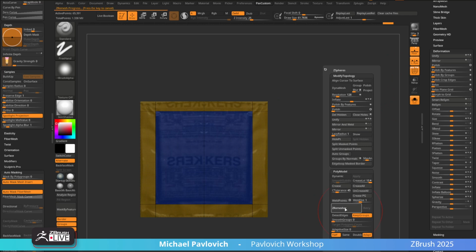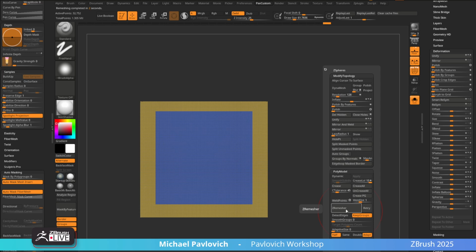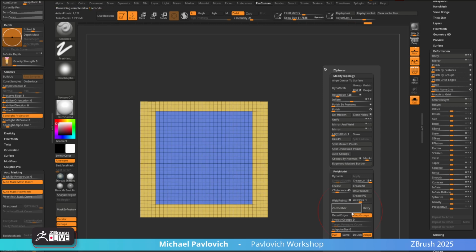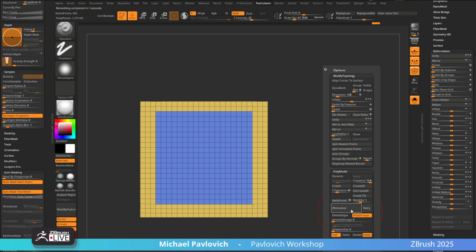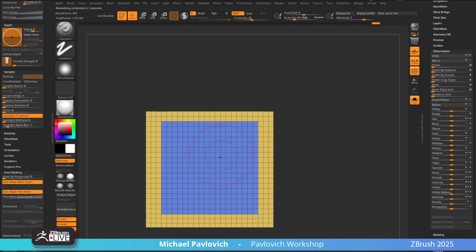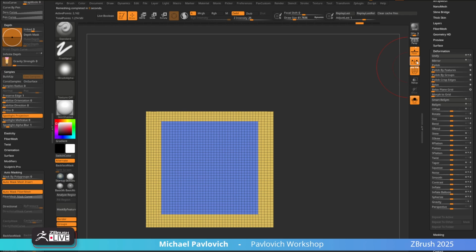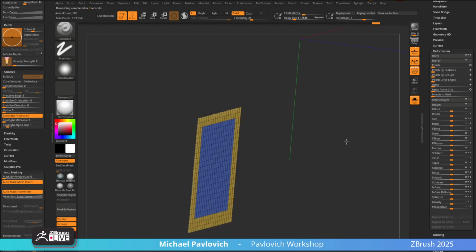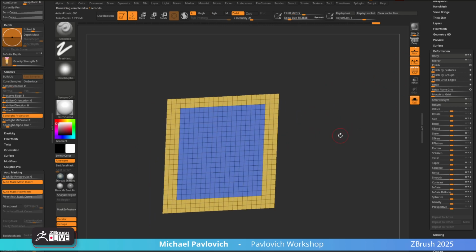I'm going faster because we've already talked about this. So go back in the video and you can see me doing it slower. And we're just going to hit half a bunch of times. So now we're getting, again, we're not making a game res necessarily, but we could. We're just getting something lower basically. Also, while we're doing this, if we want it symmetrical while we're doing ZRemesher half, just turn on X. We have LSym turned on, so it's across the local axis of this object, and we're good to go.